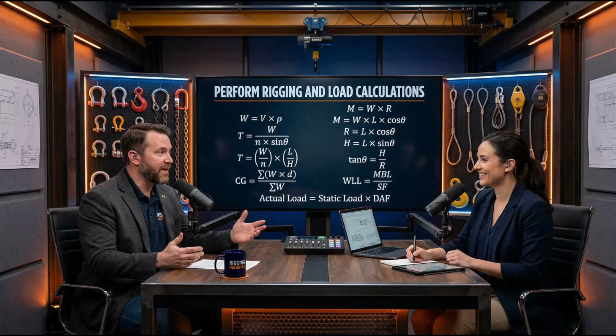Because of tiny millimeter scale differences in the manufacturing of the wire ropes, slight stretching from previous lifts, or microscopic shifts in the center of gravity, a rigid load will almost never distribute its weight perfectly evenly across 4 distinct lifting points. It's physically almost impossible. Invariably, 2 legs situated diagonally from each other will snap taut and absorb the massive brunt of the weight. The other 2 legs are essentially just along for the ride, just acting as stabilizers to keep the load from spinning out of control.